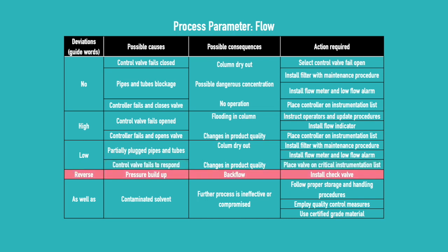As for reverse flow, it may be caused by pressure build-up, which leads to backflow. Therefore, a check valve needs to be installed to prevent that from happening.